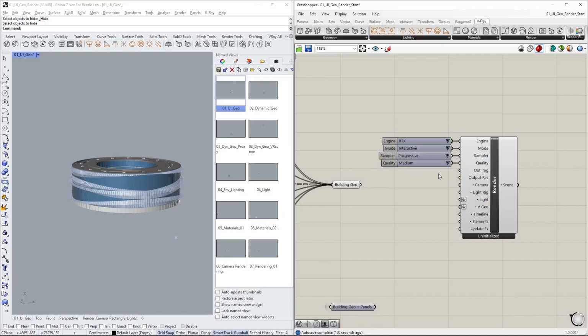In addition, it is good to create and connect a V-Ray denoiser component before initializing the render process. It applies a denoising operation for smoother image output without sacrificing the render time too much. Since I'm already rendering on the GPU, it's best to leave denoising to the CPU and switch to Intel's Open Image Denoiser. For the final image, it's best to use V-Ray's proprietary denoiser, as it is the most accurate for high-quality renders.